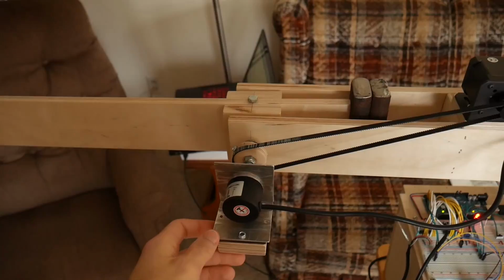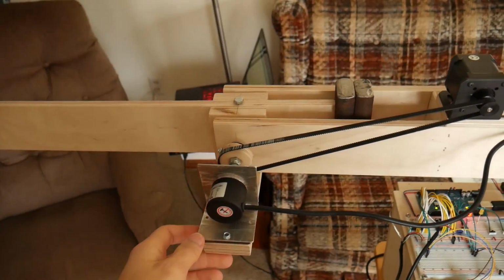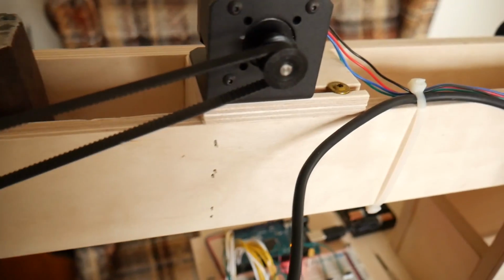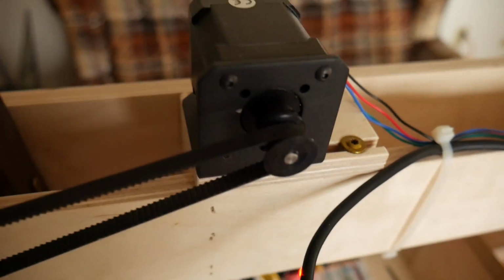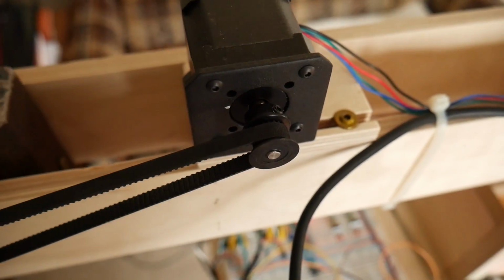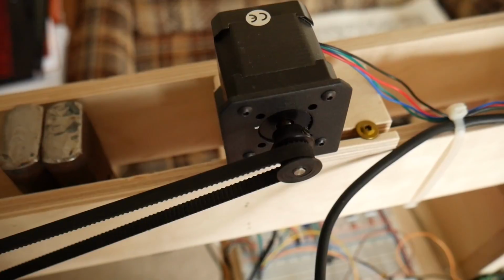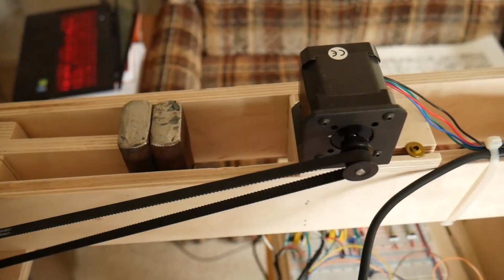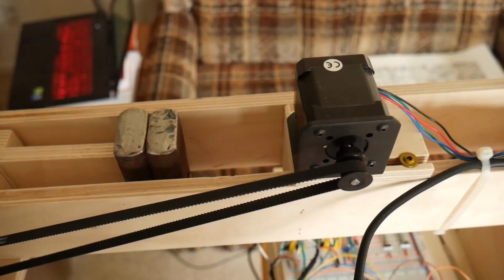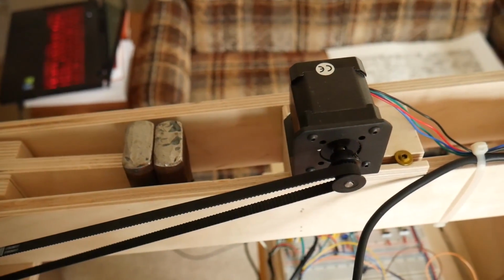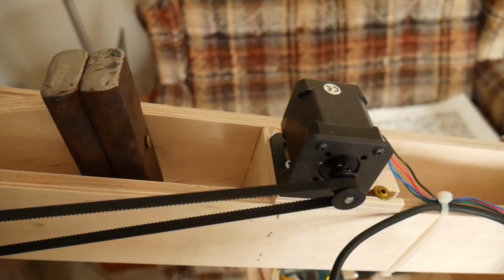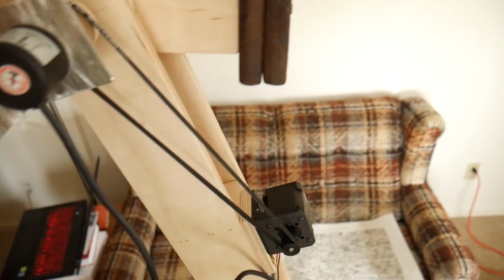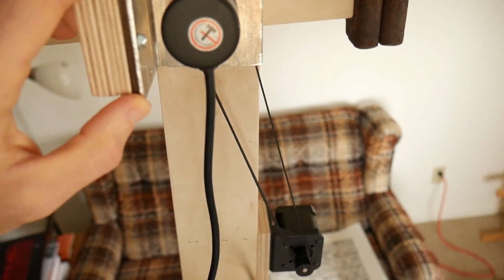I think part of it is that the upper arm has a very high tendency to rock back and forth. It has a lot of inertia, and the stepper motor, even when I cranked up the frequency so that it wasn't stepping as far, puts inputs in a step function. So it's a step and a step. And so even if you step forward and it overshoots and you step back, it didn't seem to be working. And then the belt adds some flexibility there.